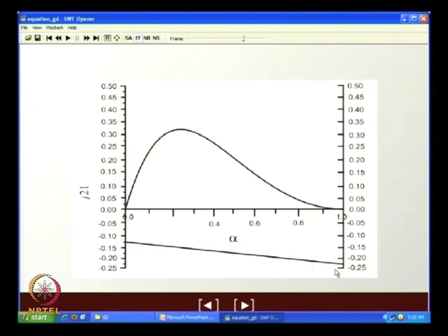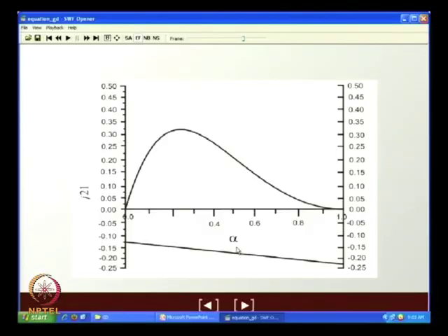And therefore, what do we find? For such a flow situation, there cannot be any point of intersection between this curve and the straight line. Quite expected. Have you ever found any countercurrent operation with gas down, liquid up? This cannot be a stable situation. We cannot have anything where the gas is going down and the liquid is going up. Countercurrent means gas up, liquid down. Okay? So, from this particular curve we find that such a situation is not possible, which you already know.